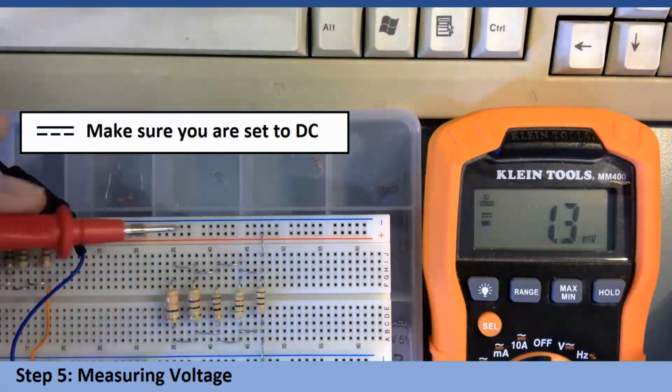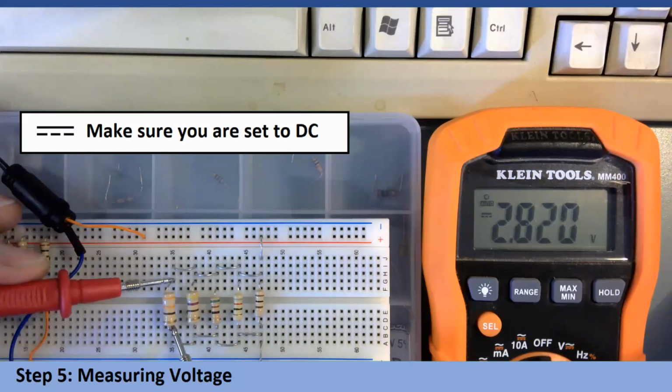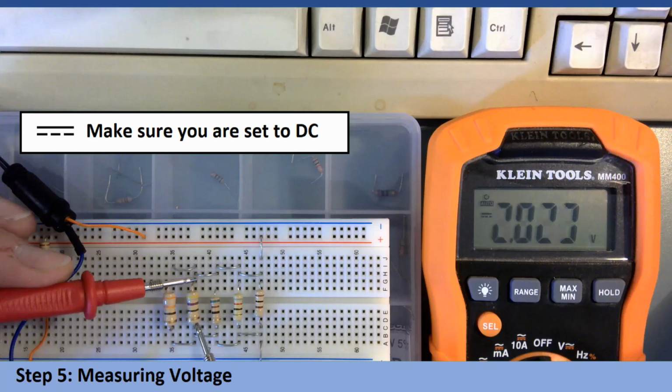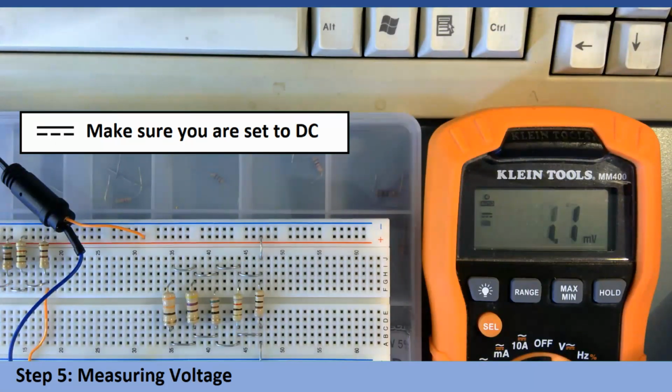So let's check our voltages again. This time we're mindful of it. 2.82. My power supply does not put out a perfect 3 volts. 2.82. So you are going to carry on and measure all of the voltages across each of the resistors.